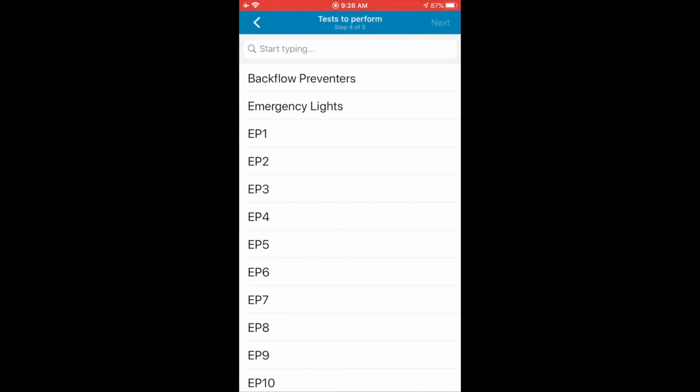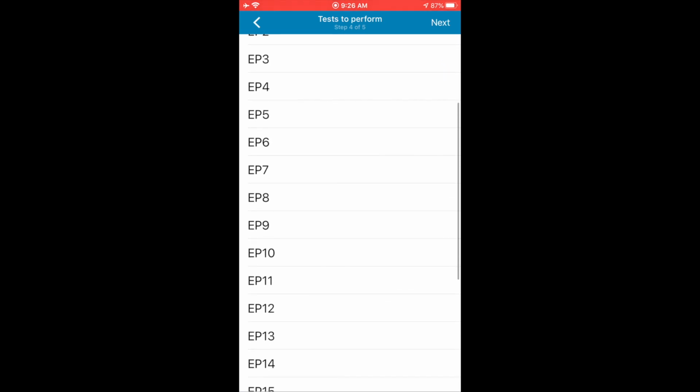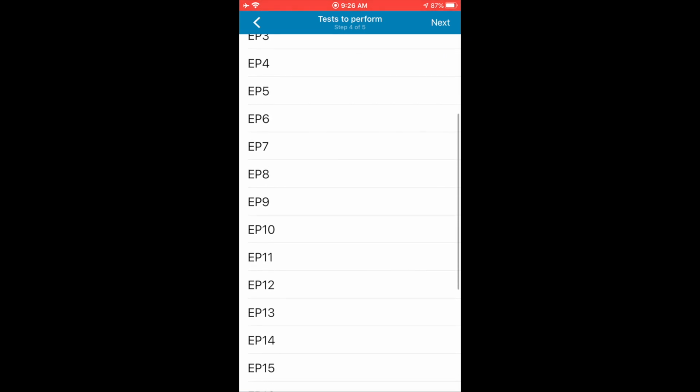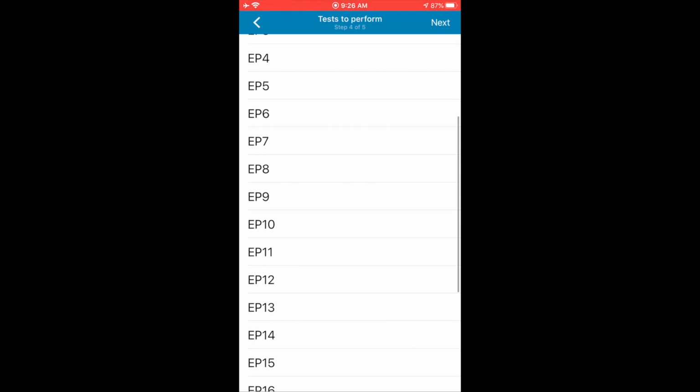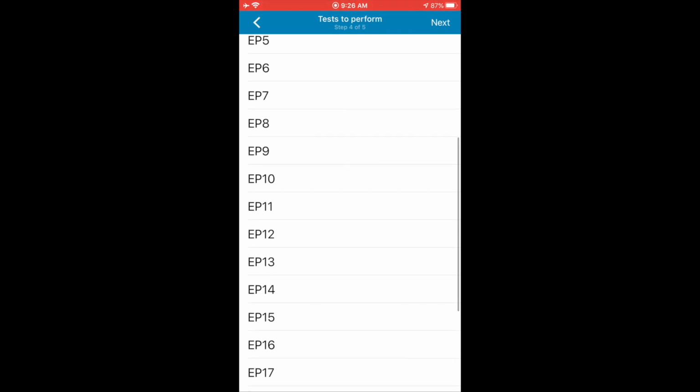I'm going to select EP1 because I do have a dry system. I'm going to select EP2 because I want to do my flows and tampers. I'm not going to select EP5 because I'm not testing the communication on this particular inspection. And I'm not going to choose EP6 because I'm not performing a fire pump monthly or weekly. I'm not going to choose 7 or 8 because I don't have a water tank here.